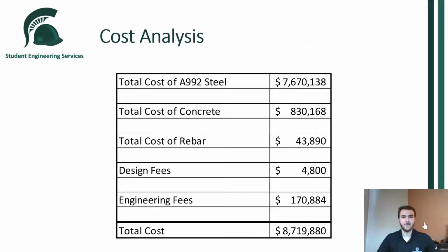With the shape of each member known, the cross-sectional area could be determined and multiplied by the length of each member to come up with the total volume of steel used in the structure. This volume could be multiplied by the unit cost of steel, and when factored with the fabrication, erection, and connection cost, created the total cost of steel.